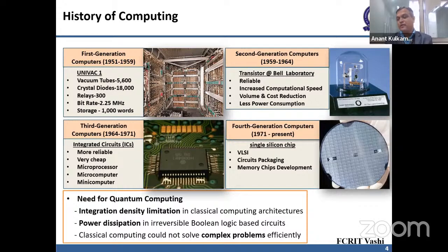Now we need to understand what we mean by this. All of us have understood Boolean circuits and Boolean logic. But have we understood the difference between irreversible Boolean logic and reversible Boolean logic? Let us take an example of a NOT gate. For 0 input it provides 1, and for 1 input it provides 0, right? If you look at the NOT gate, just by looking at the output, we will be able to know what the input was. But the same case is not applicable with the remaining gates. Take the example of the AND gate, the OR gate, the XOR gate, even more complex circuits like the full adder or half adder. The moment you see the output, you lose the information about what was at the input.